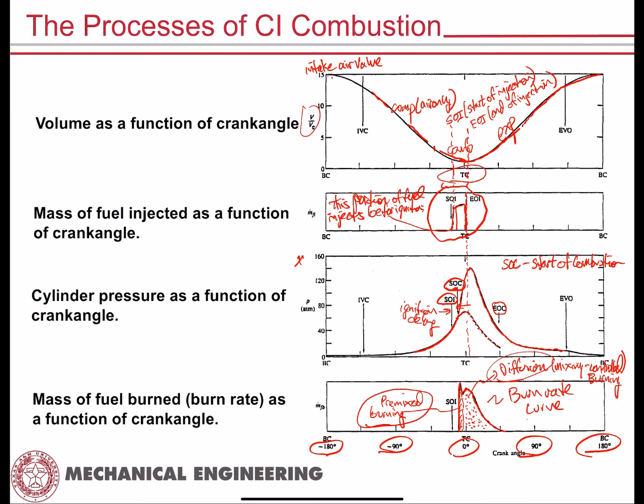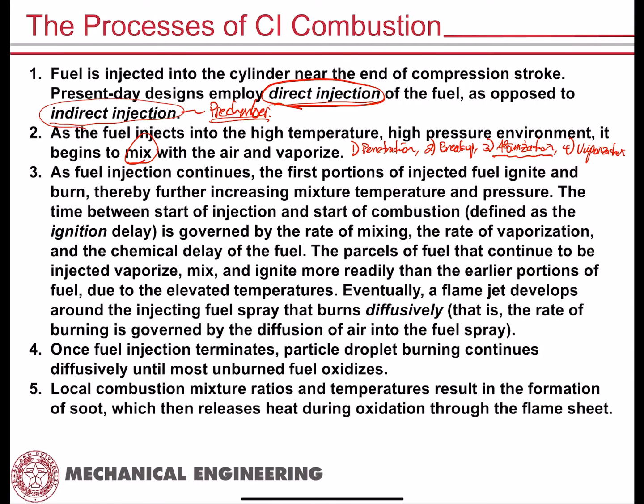As that fuel is injecting, it's undergoing these four processes of penetration, breakup, atomization, and vaporization before the combustion reaction actually starts. And so you will have a quantity of fuel that has done these four things at the moment that they're at a high enough temperature to actually begin to chemically react.